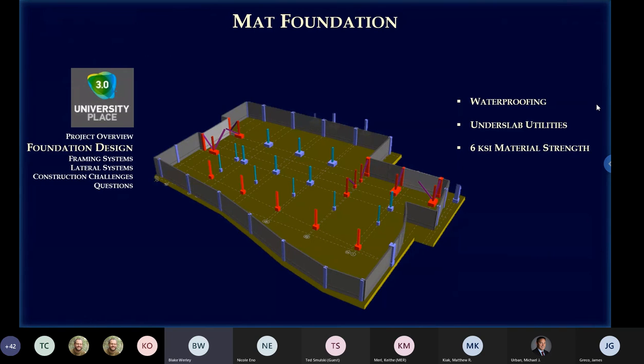So we led to a mat foundation just to simplify the waterproofing details and for confidence that it would be watertight. So we designed a 3-foot mat foundation.